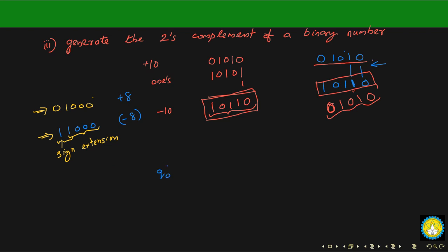So let's start at Q0, and remember, until you are getting a 1, whenever you are getting a 0, you're going to output a 0, right? We are scanning from left to right. So whenever we are getting a 0, our output is also going to be 0. And when we are getting the first 1, again the output is going to be 1. And whenever we get a 1, we are going to a new state, just because we want to have different transitions there.